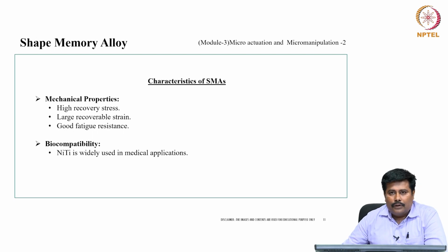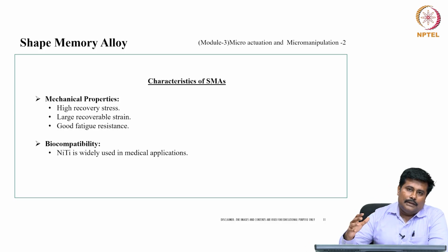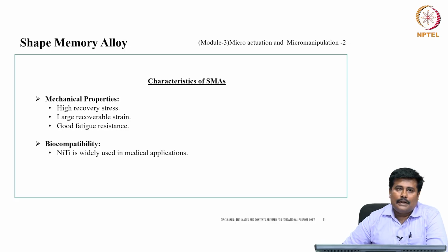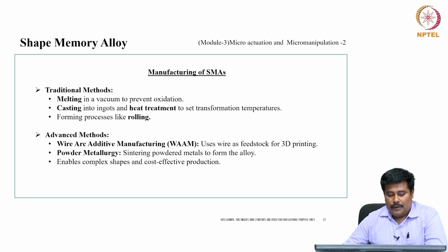Now, when I talk about the characteristics of shape memory alloy, it has good mechanical properties: a high recovery stress and a large recoverable strain. It also has good fatigue resistance, and as discussed with respect to biocompatibility, NiTi is widely used in medical applications.